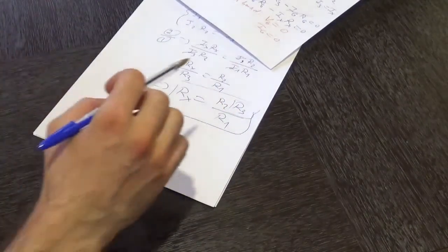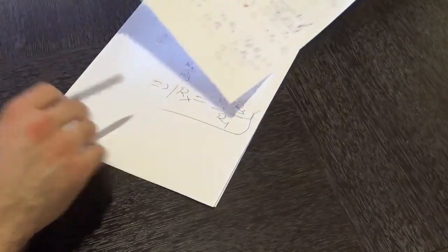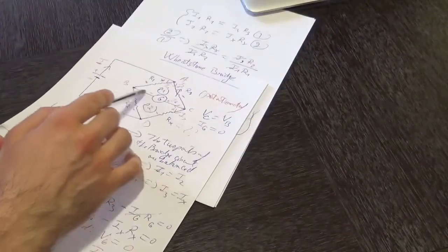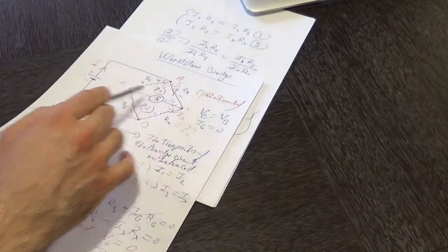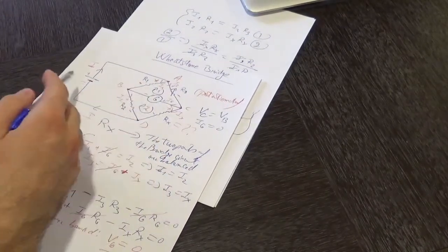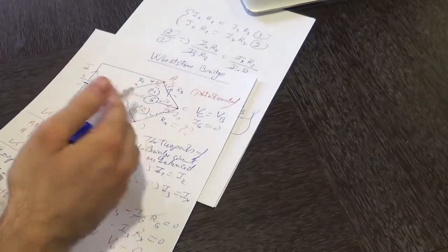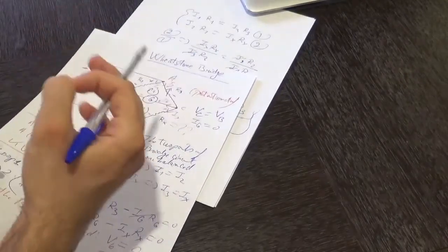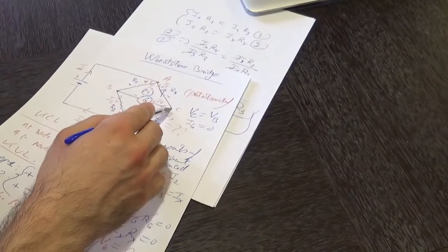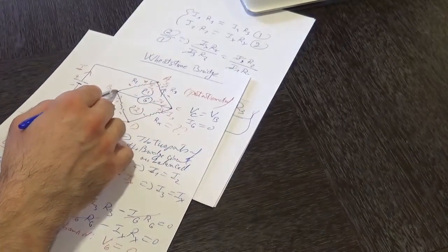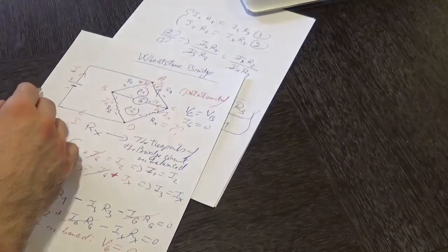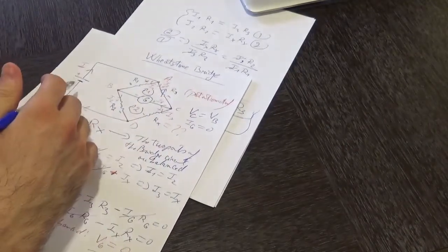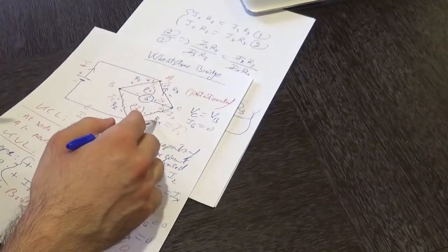resistor. Once you keep varying that variable resistor, you are varying the potential difference between B and C. So you keep varying R3 until the galvanometer is reading a potential difference between these 2 points of 0 volts. In that case, the potential at point C would be equal to the potential at point B. Therefore, the bridges are balanced and you don't have any current flowing through them. Once they are balanced, you can get a reading for Rx.